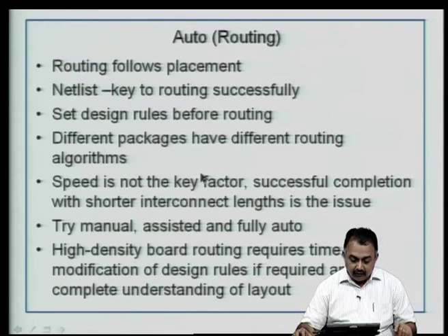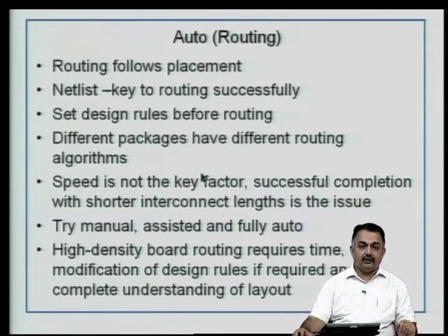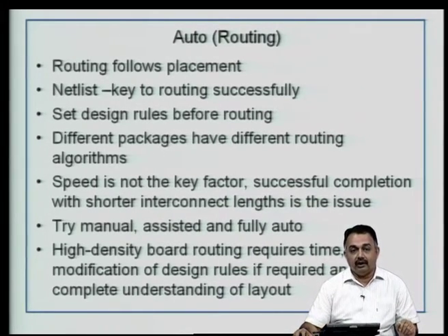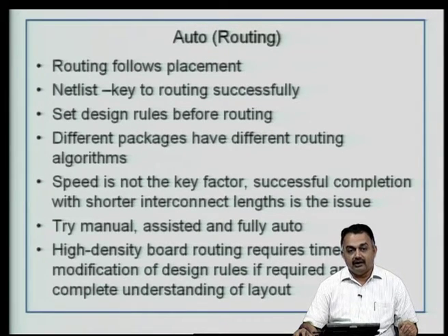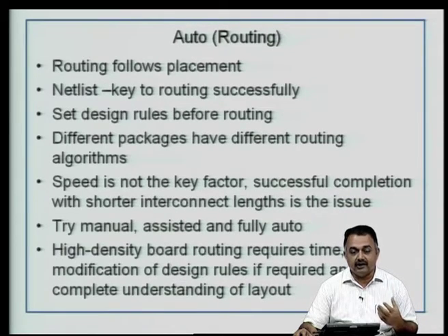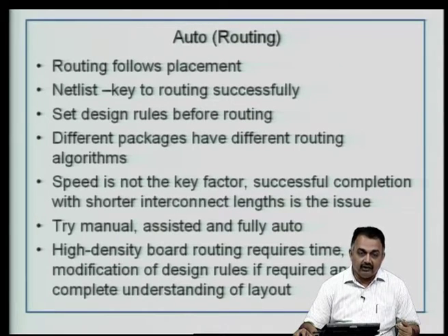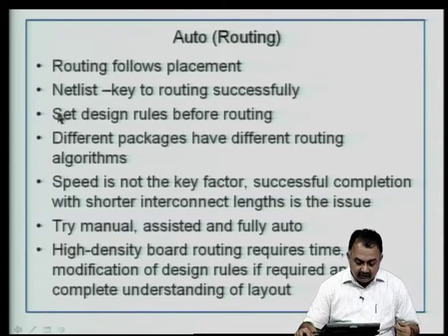Now, after the layout module, obviously you are going to do the routing. You can also do an auto routing or a combined assisted routing, but a typical designer will spend a lot of time using manual routing, because you understand exactly where the components are and what typically the net routes have to be in terms of line width and spacing and so on. So, routing follows placement. Netlist is a key to routing the board successfully. Set design rules before routing, we have seen some of them.